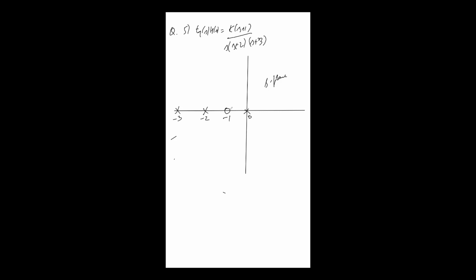So this will be part of my root locus. K is equal to 0 is here, k is equal to infinite is here. This will start from here and it will terminate at infinite. This is k is equal to 0, at the open loop pole the value of k is 0. If you are at this point, see this will be part of my root locus. So there must have been a breakaway point.